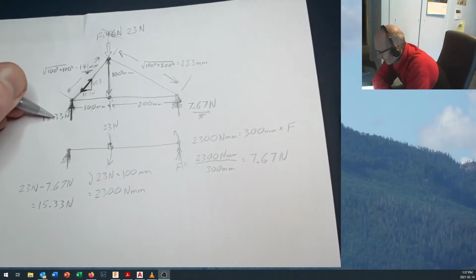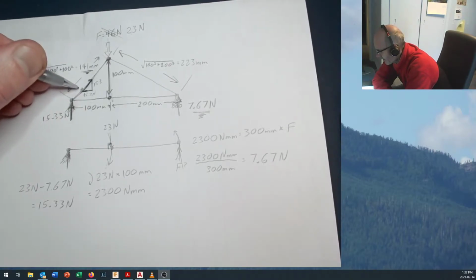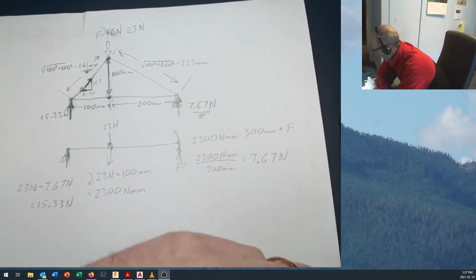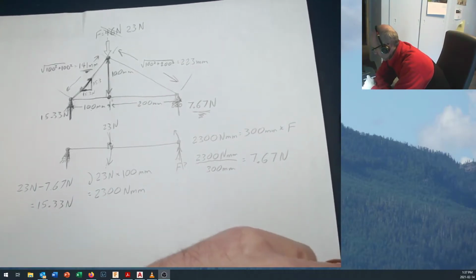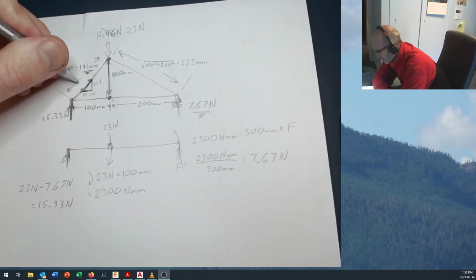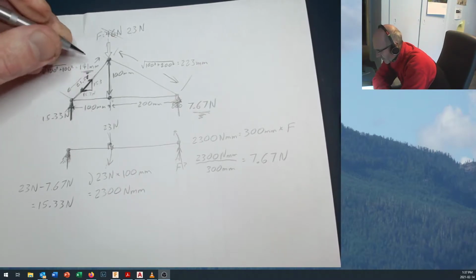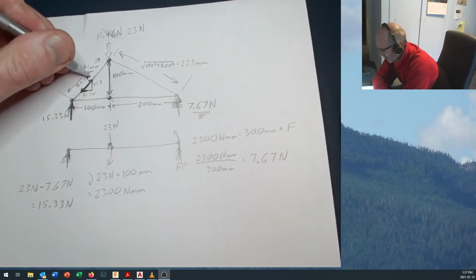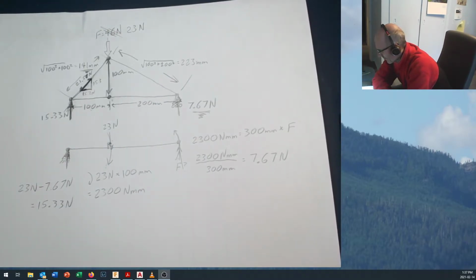And if I take 15.3, divide by 100, and multiply by 141, that means that the overall compression in that member is going to be 21.57 newtons. I was going to say, could just round that off to 21.6. We do have margins of error approaching 10% right in here. So, yeah, keeping too many decimal places doesn't really make that much difference.